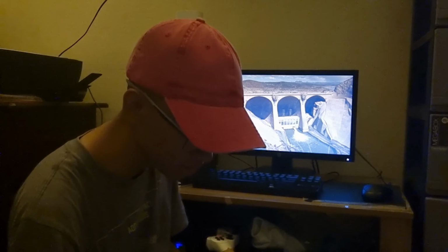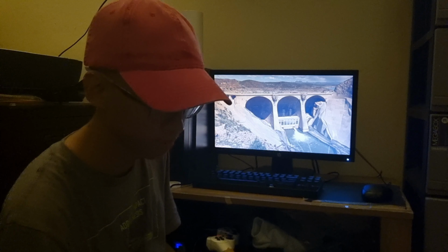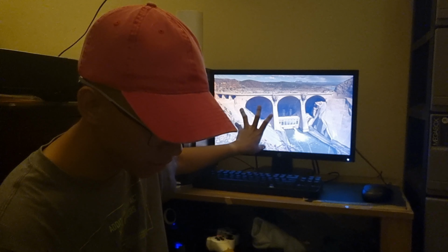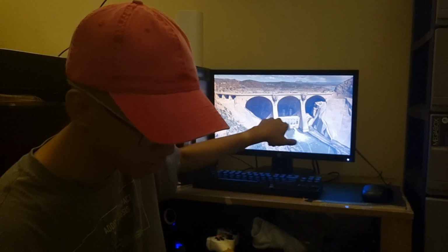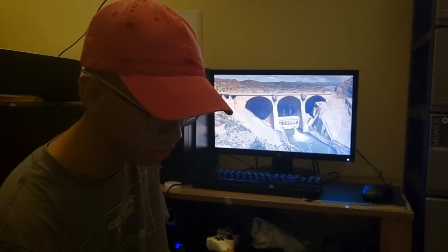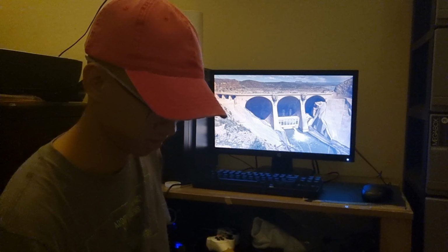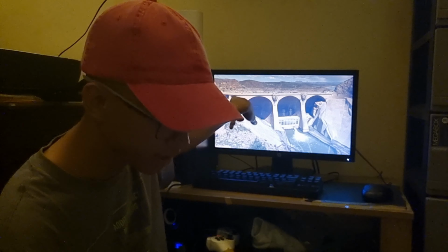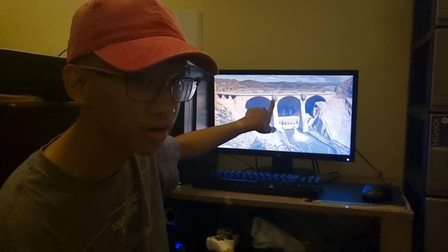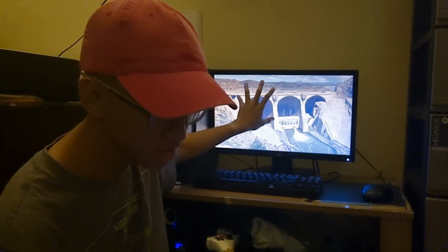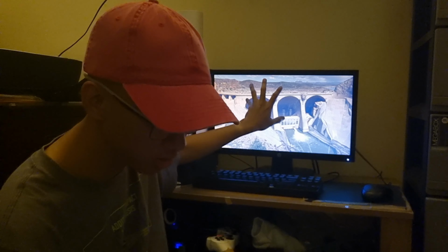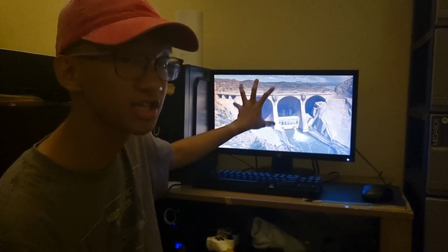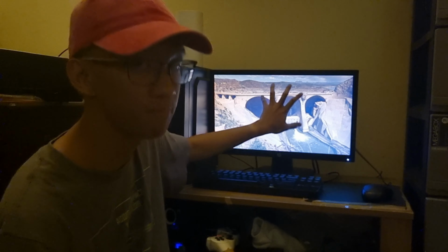Alright, last one is called an arch dam. This one is the East Canyon Dam in Morgan, Utah, and it's a concrete or masonry dam which is curved upstream so as to transmit the major part of the water load to the abutments. Essentially, you don't need to listen to all that. The basic description of this is essentially a double curvature arch dam. So it's curved vertically as well as horizontally. You just can't see the curve because of the angle of the picture.